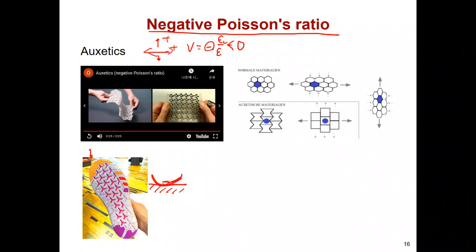That means they will experience this kind of longitudinal direction. But conventional material experiences positive Poisson behavior. That means this part shrinks, so your shoes will press your foot and it will hurt. However, if they show a negative Poisson behavior in this direction, your foot will feel comfortable. So the negative Poisson ratio can be used for those kinds of applications.